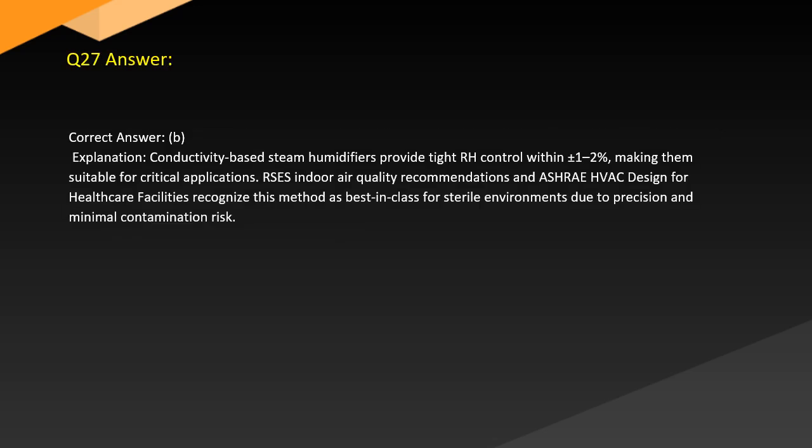Answer. Correct answer: B. Explanation: Conductivity-based steam humidifiers provide tight RH control within plus or minus 1–2%, making them suitable for critical applications. RSES indoor air quality recommendations and ASHRAE HVAC design for healthcare facilities recognize this method as best in class for sterile environments due to precision and minimal contamination risk.